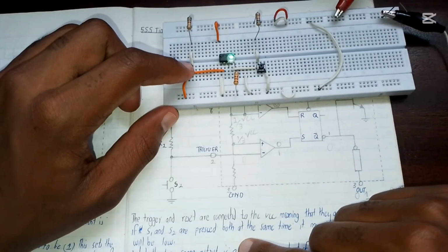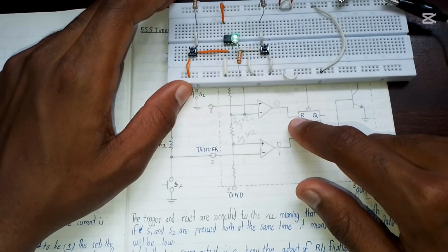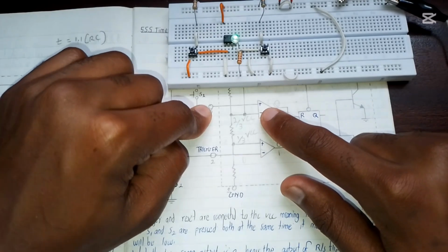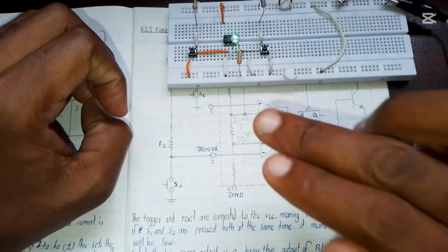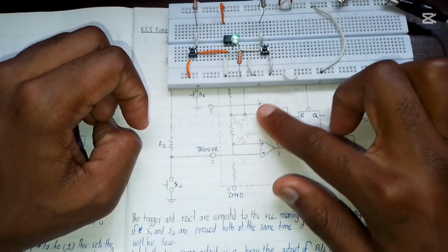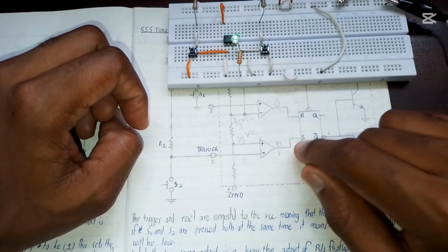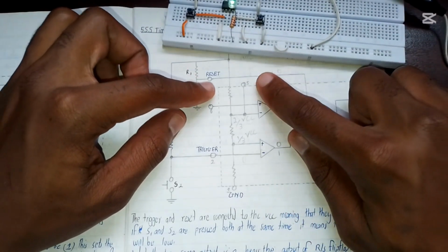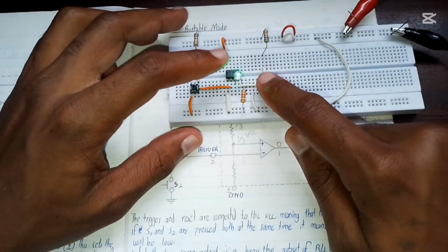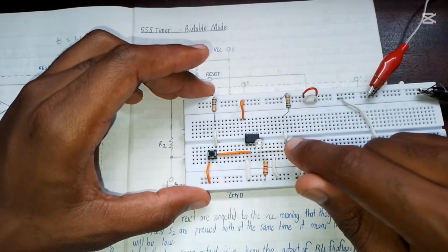Even if I press it one more time, nothing is going to happen because the R input of the flip-flop is always 0, because the threshold pin, we have not connected it. So it's always giving a 0, meaning that this output cannot be manipulated by these inputs at all until this becomes 1. And since this cannot become 1, the only way is to press the reset pin right here. So the reset pin is this one. We have this push button, and once I press it, it's going to be turned off like that, and nothing happens. Even if I press it one more time, it cannot turn the LED on.